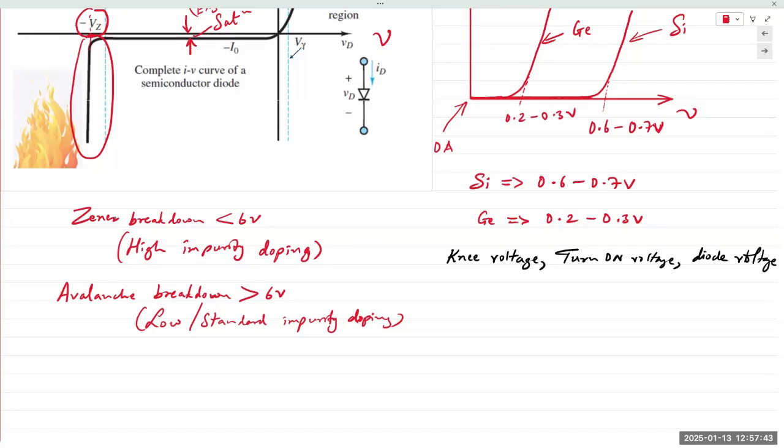Okay. So again, Zener breakdown occurs in heavily doped diodes. They are specifically designed in such a way that breakdown occurs. And then there's impact ionization that occurs at larger than 6 volts, meaning you're increasing the external electric field. That energy is imparted to the free charge carriers. Now those in turn have enough energy to move. And once they're moving, they move at random and collide with other atoms and create more and more charge carriers. It leads into an avalanche effect, and then it leads into breakdown or junction breakdown.